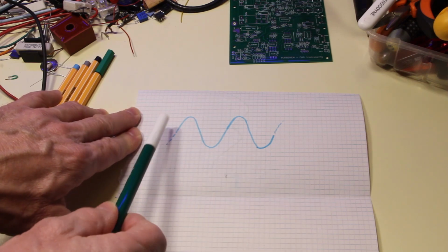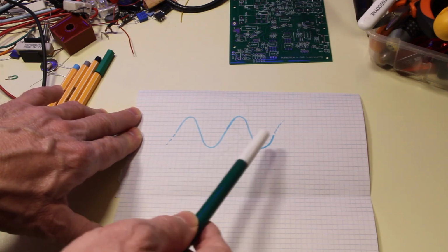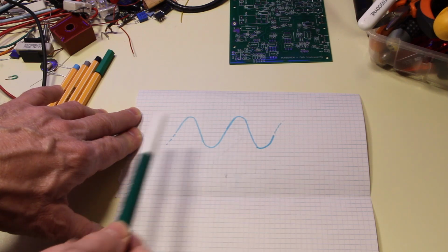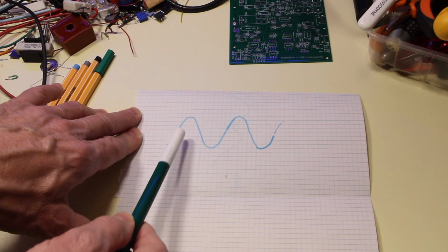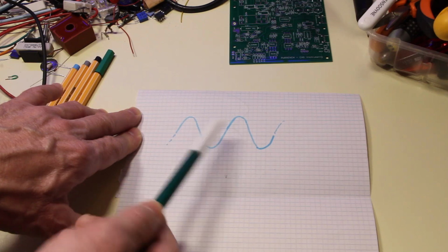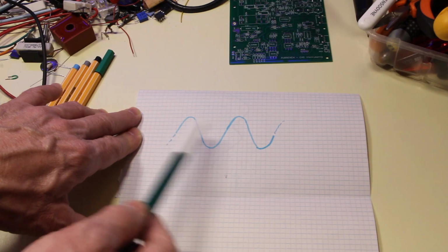Now you would wonder, what is this trigger and why is there one? All waveforms are typically periodic. It means that they repeat themselves over and over again. So when you want to display them on the screen, you have to decide at which point to start to draw the waveform on the screen.